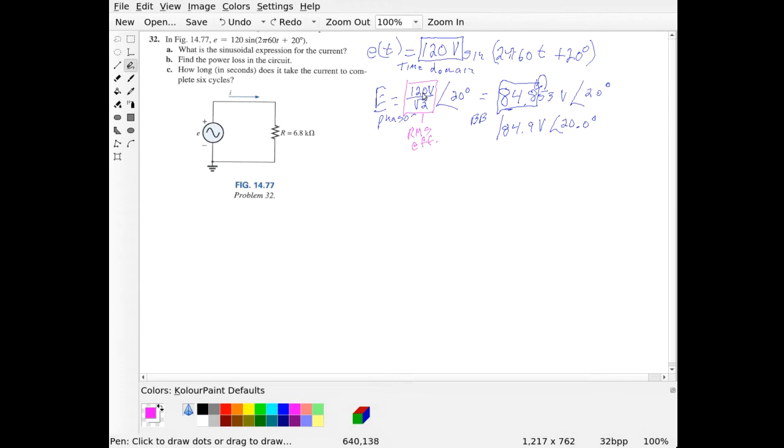Okay, now when you are going to do the actual calculations, you really want to make sure that you use like 5 significant digits. So don't use the rounded value when you're calculating currents and things, because especially when you start calculating power and you start squaring values, it will really mess up your rounding if you don't take it out to at least 5 digits.